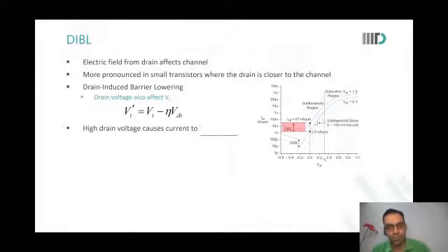Even when the VGS was less than VT, there would still be a depletion under the gate also, na? But we have not considered that in this. There would be a depletion under the gate at all times. There is some VGS, there would be some depletion, but there would also be a point where there would be no depletion.